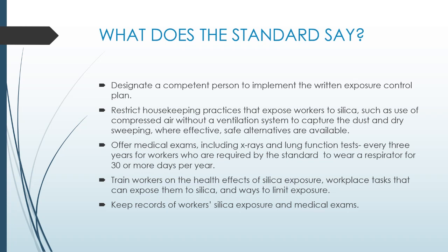The standard also requires us to have medical exams and give x-rays and lung function tests to make sure that while you're being exposed to silica, you're not being exposed beyond what's medically safe. And we have to give those to you if you wear a respirator for 30 days or more a year. This training is going to include the health effects of silica exposure and what to look for, the signs and symptoms of what happens when you're exposed to silica, and then keeping records of your silica exposure and medical exams.